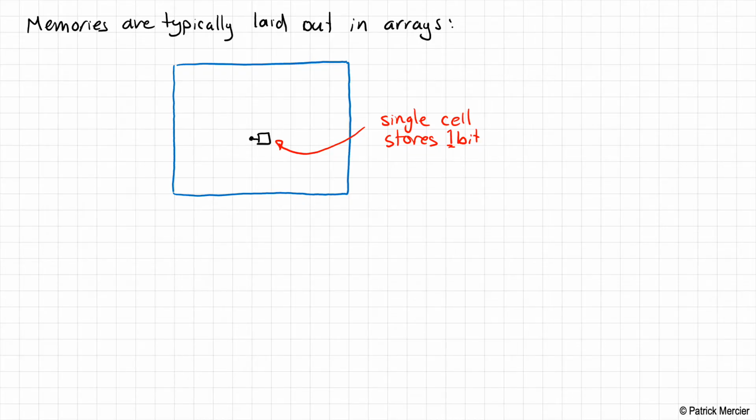Okay, and we read out typically through a row-column architecture, where we activate a row within the memory and activate a column and then read out that 1 bit. We call this column the bit line. This is the column that's going to actually read out the stored data. And this is called the word line. It's called the word line because we can activate a whole line at once. This will activate a readout process, and we can activate multiple bits at once, so perhaps we can read out a whole word, a digital word, right?